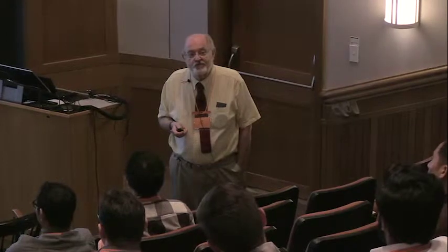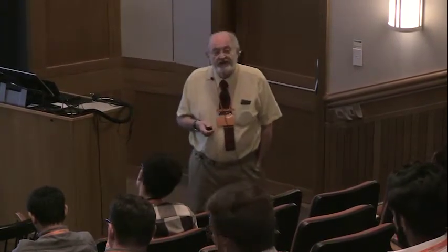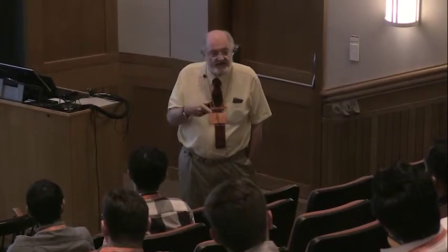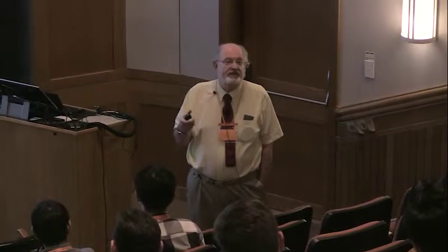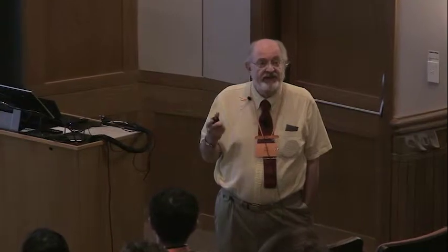It's always useful to use a simulation because it's cheaper compared to the experiment. Is there any threshold for us to switch from using 1D simulation into 3D simulation? Like if there's a certain compression ratio or something? That's a good question. So I showed you, I hope, yesterday that to use the 0D or 1D models requires calibration against something. So if you have an experiment, great, use that. But if you don't have an experiment, or you're looking at a new combustion strategy that you've never seen whether it operates or not, you do need to use simulation tools.